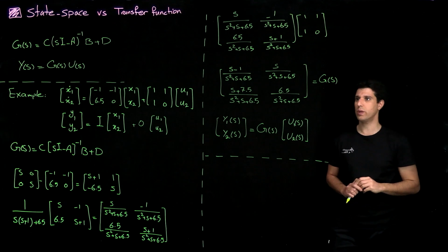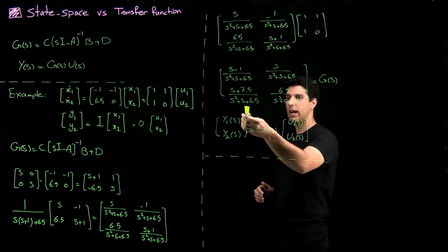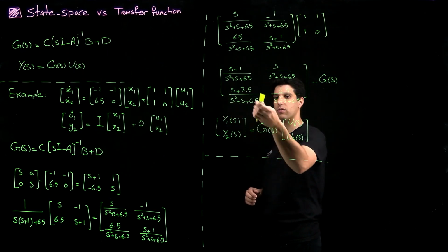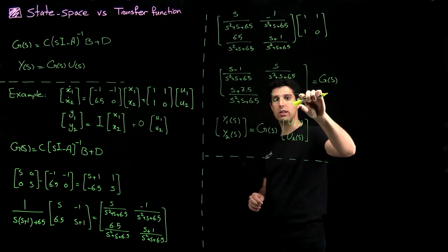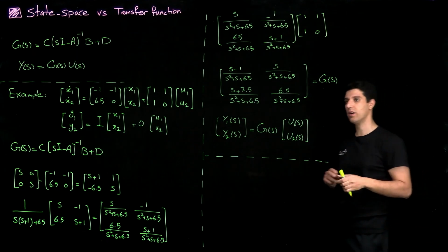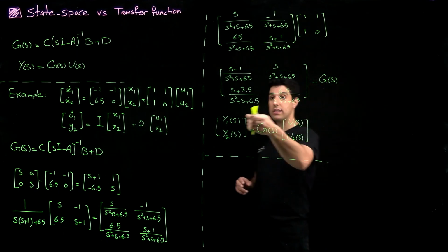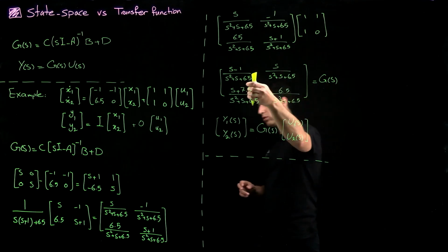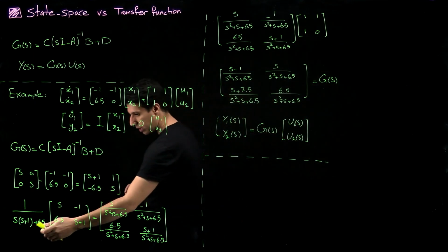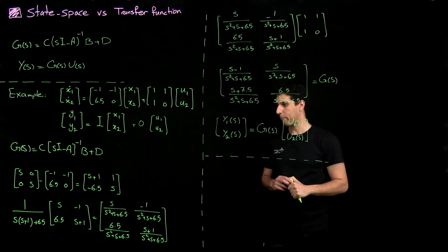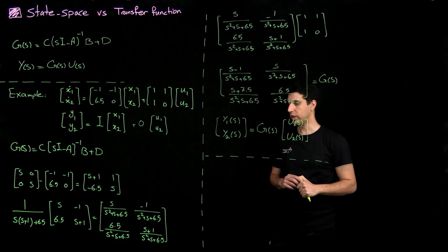And this is not a coincidence that the characteristic equations for each of these transfer functions, essentially the denominator of each of these individual transfer functions, is the same, first of all, based on all of those, and also it is the same as the determinant of the A matrix.